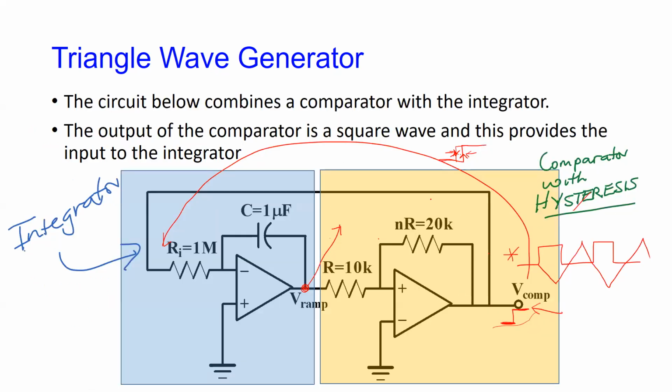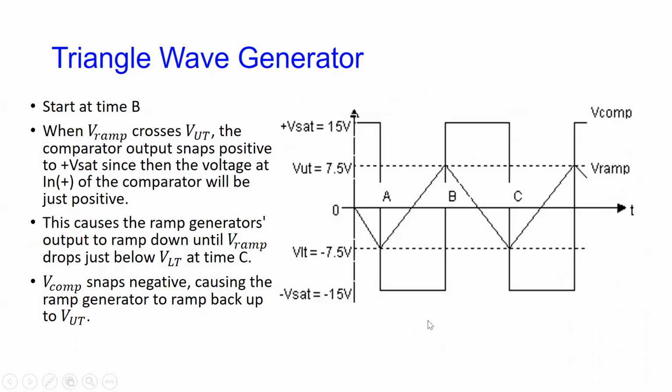Remember, these two here are setting up a switching voltage, a comparator voltage, so that at the point when the ramp voltage crosses whatever that voltage is, it flips again and it just keeps flipping back and forth. So the net result is that you have this triangular wave.